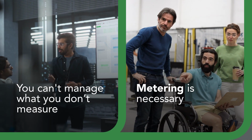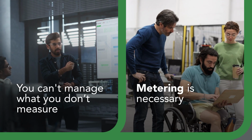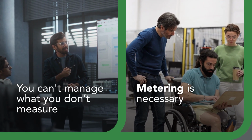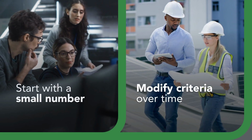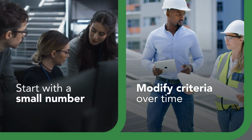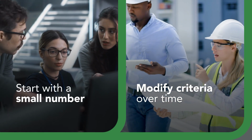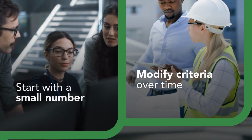Remember, you can't manage what you don't measure, so it is necessary to have some metering capabilities at the equipment or system level. Organizations often start with criteria that capture a small number of significant energy users and then modify those criteria over time to capture additional equipment.